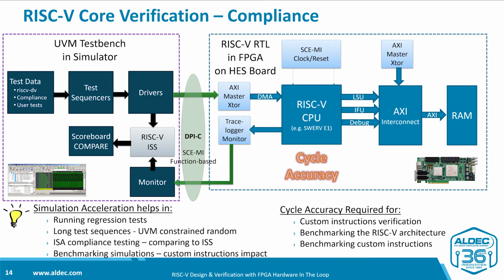And by using SCE-MI, we achieve interoperability of the UVM test bench, which can now be used either with the design simulated or emulated in the HES-FPGA board. Aldec HES-DVM allows for compiling the RISC-V CPU along with some test bench components like transactors, monitors, and also a clock generator into FPGA.